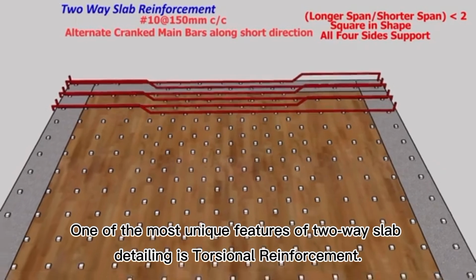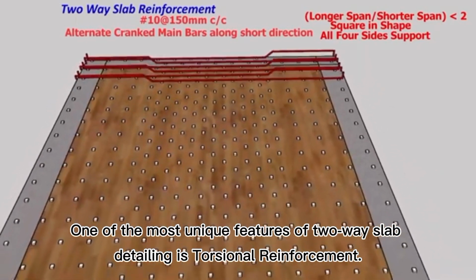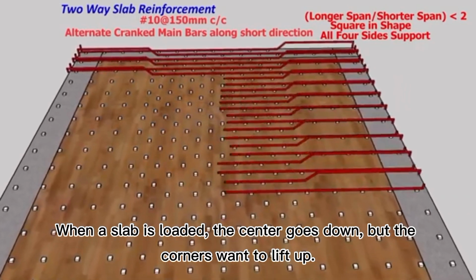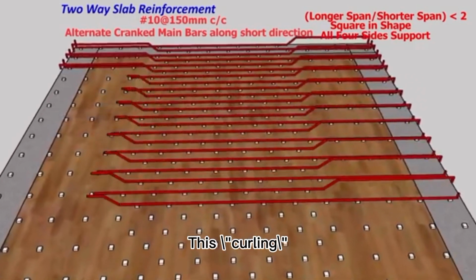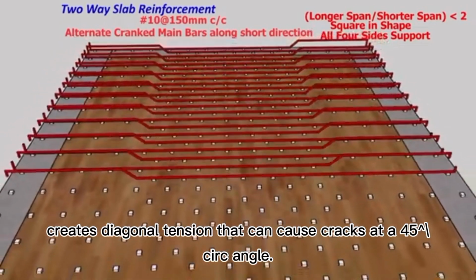One of the most unique features of two-way slab detailing is torsional reinforcement. When a slab is loaded, the center goes down, but the corners want to lift up. This curling creates diagonal tension that can cause cracks at a 45° angle.